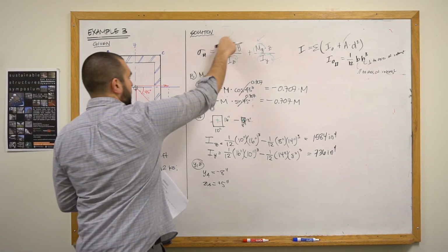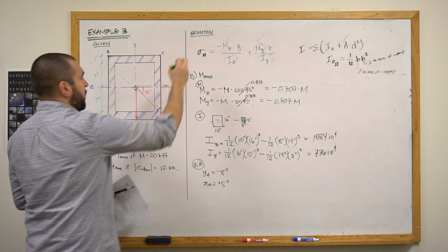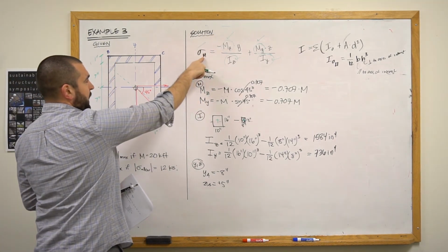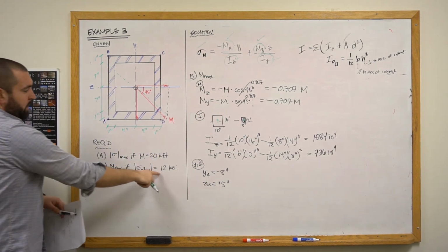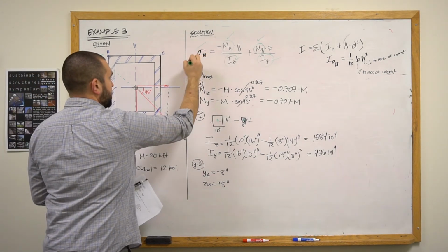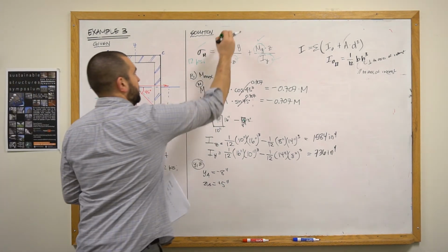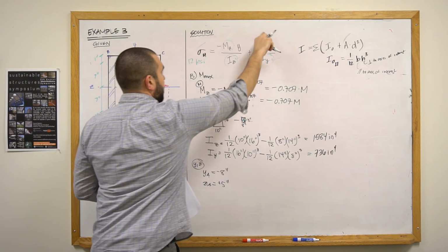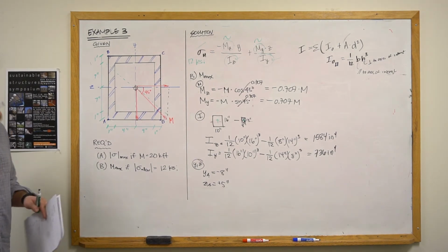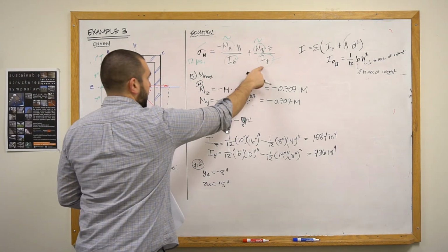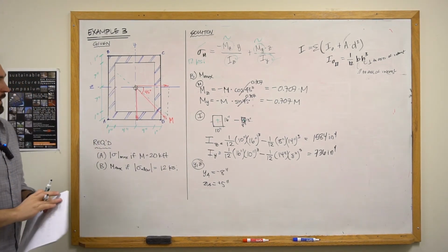So at that point we do have Mz as far as we can get it. We do have My as far as we can get it. And I would also point out that now we have sigma max, the largest normal stress that we can get is 12 ksi, and so I'm going to put that here as well, 12 ksi. So I'll put kind of a squiggly for the moments because we've broken them down as much as we can. There's still some unknowns, but we've gotten them simplified as much as we can. Now, Iz and Iy don't change based off the loading. That is a geometric property of the cross-section, and so that stays as it is.